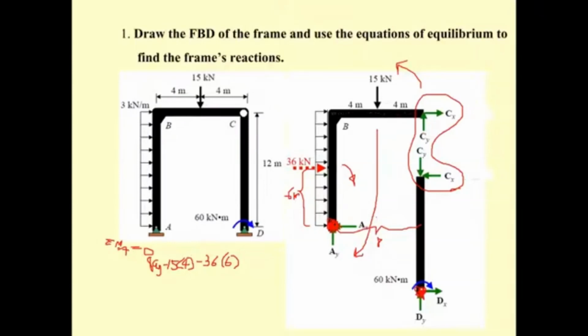And then you still have c sub y, in which c sub y has this moment arm, and c sub y is going to rotate like this. So you've got to have minus what? C sub y is going to time the whole of this, which is going to be 12 meters. So c sub x times 12 meters, and then you have this equal to 0 for your first equation, and you can rearrange it. You may have 8 c sub y minus 12 c sub x equal to this term. You can do it by yourself.